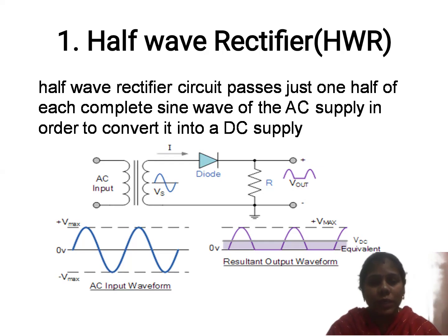Now the potential at the anode is negative and the potential at the cathode is 0. So the voltage across the anode is less than the voltage across the cathode. If this condition is satisfied, the diode works under reverse bias. When the diode is under reverse bias, it acts as an open circuit.